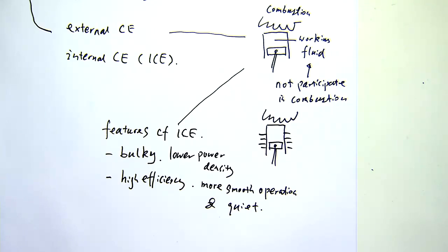That's the one showing here. So the Stirling engine has been used in submarines. And the reason for that is that for a submarine, the power density is not a big concern. So if you consider the three types of transport: air, road, and water, they have different requirements in terms of power density, or power to weight ratio, right?